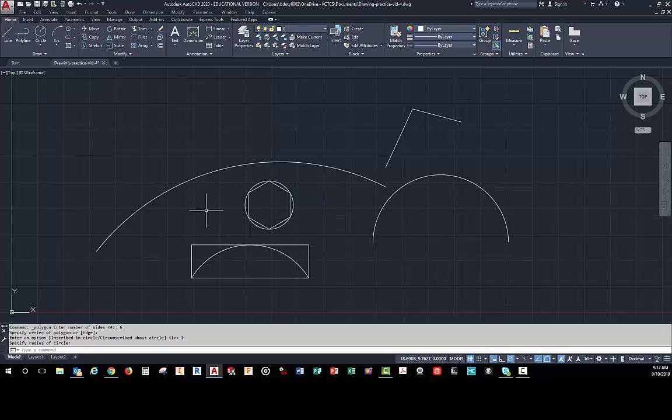So let's put it inside the circle, and let's just do like that. The circle that we drew, or used as the radius, and that's the other thing, the dimension you're given is always a diameter, but yet the dimension that you need to use for this is a radius. Another miscommunication between whoever designed this versus actual drafting practices. Anyway, this is on the inside, and you'll notice that the corners are touching the circle. So this is the distance across the corners, which would be the diameter.